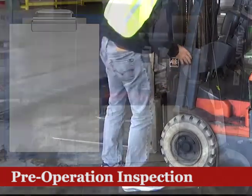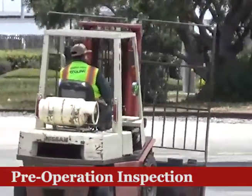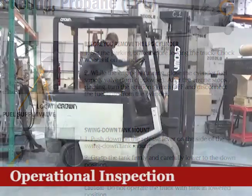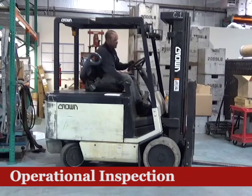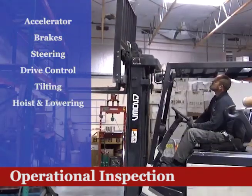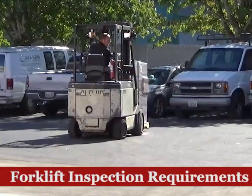Different types of forklifts will have their own unique inspection requirements. Electric, internal combustion, and liquid propane forklifts will all require checks on their fuel systems. Refer to the operator's manual for more detailed information. After the pre-operation inspection is complete, the driver should complete an operational inspection, with the engine running. This inspection should include checks of the accelerator, brakes, steering, drive control, tilt control, hoisting and lowering controls, horn, lights, safety devices, and any other items recommended by the owner's manual.